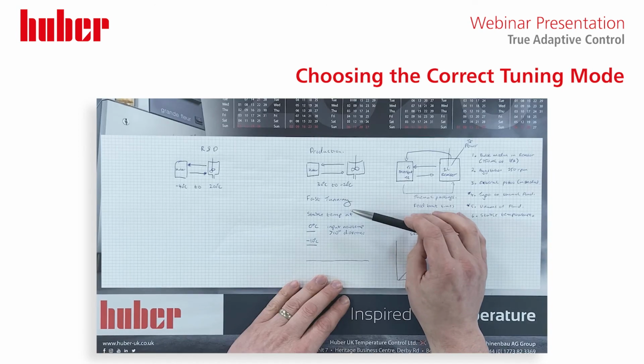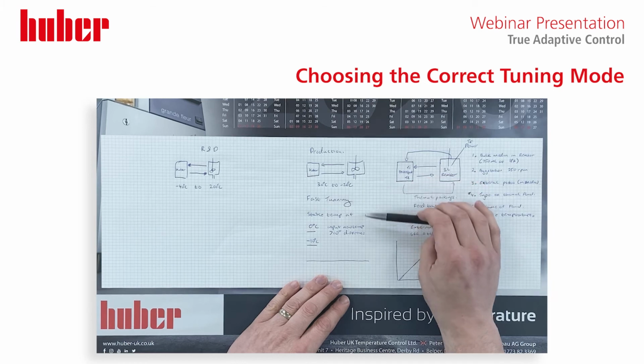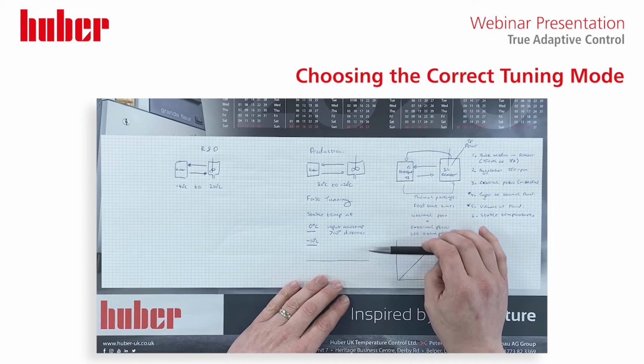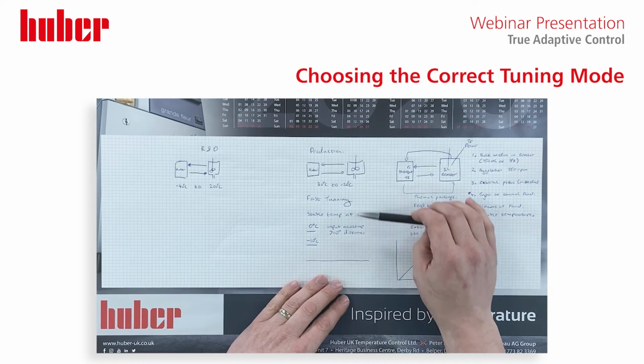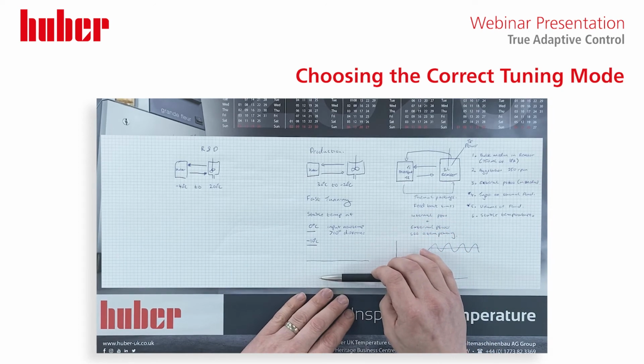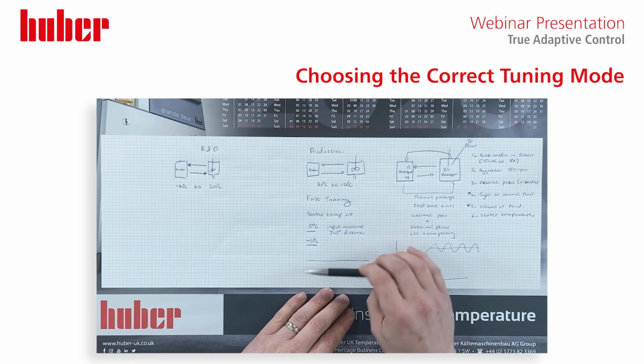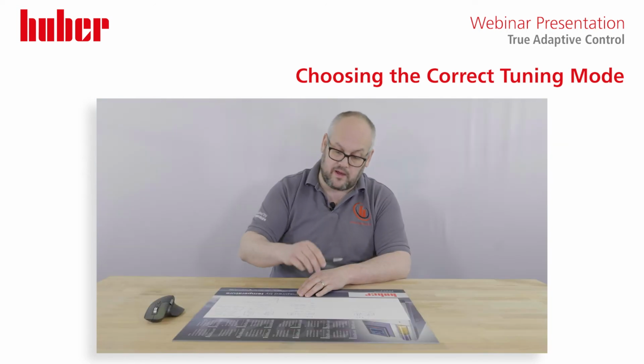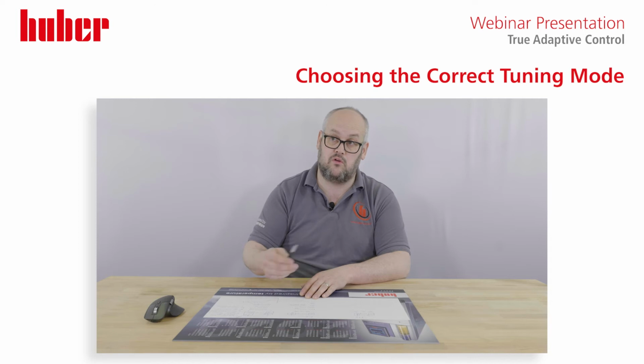So, if you're doing a one function reactor, fast tuning is fine for either heating up or cooling down. And then you can also adjust the control dynamics to tighten that control once you've done your PID tune. So if you think back, we mentioned fast with overshoot or no overshoot.